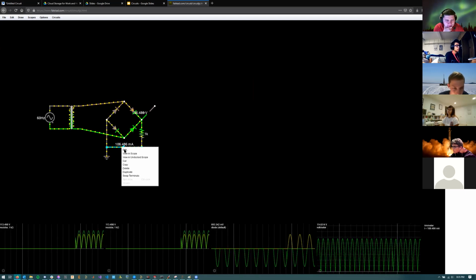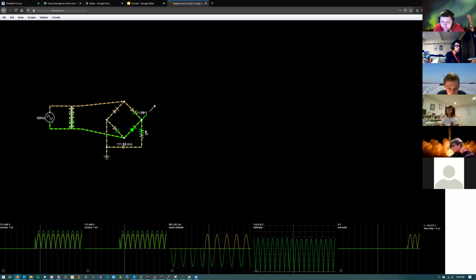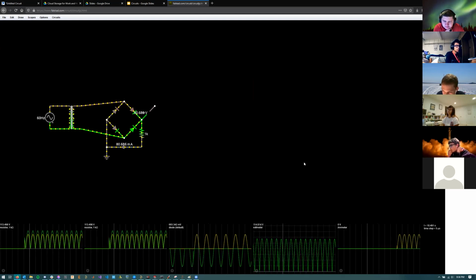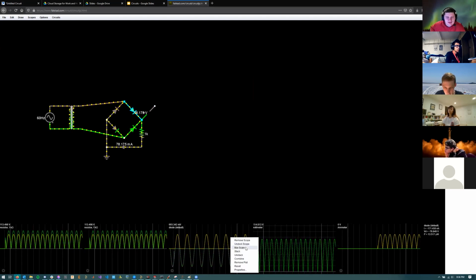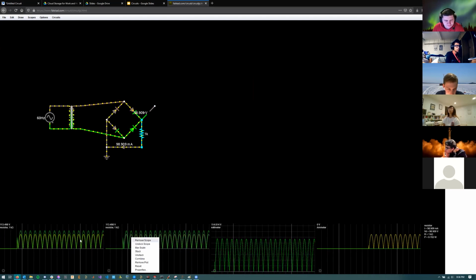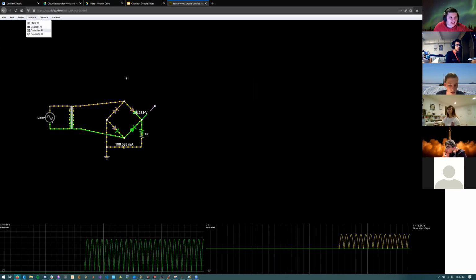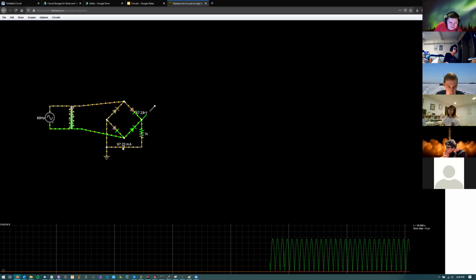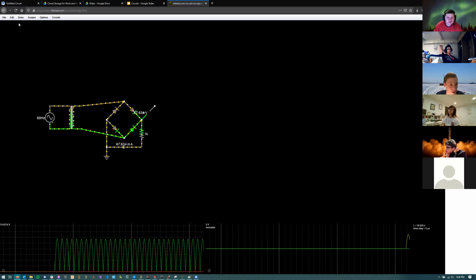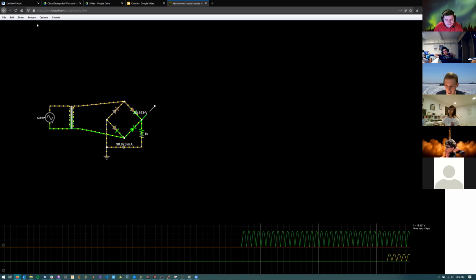So if we look at the ammeter, I want to show the ammeter and the voltmeter on the same plot. If you delete the other ones, you can go to scopes, remove scope, and then go to scopes at the top, draw, and you can combine them. Stack. Or no, you don't want to uncombine. Okay, draw, scopes, stack all. Yeah. Okay.